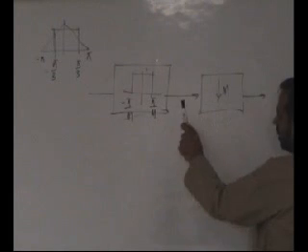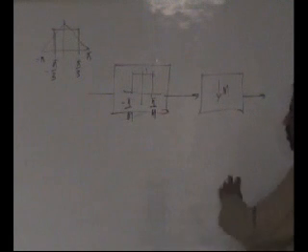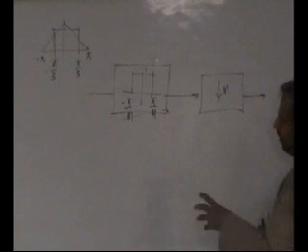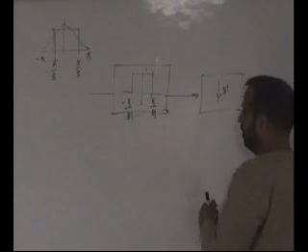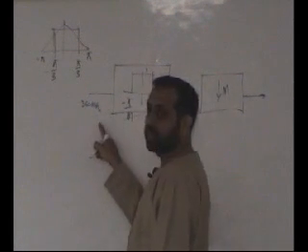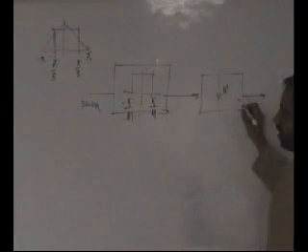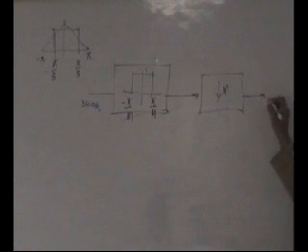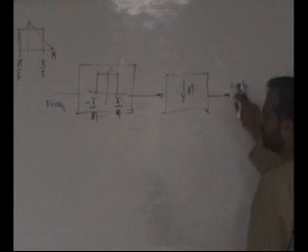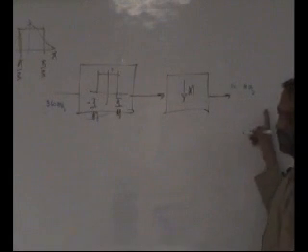To answer this, there is polyphase filtering, which effectively uses the fact that you only compute what is required. If you think of this in terms of hardware, remember, let's say here the sampling is at 360 mega samples per second, and you intend to decimate by 36, so here the sampling rate will only be 10 megahertz, 10 mega samples every second.